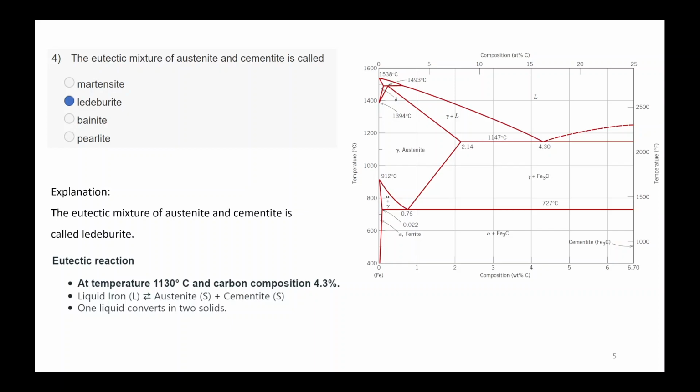Then below that, they have given two lines, the martensite start, MS, and the martensite finish, MF. Start and finish, yes. So above coarse bainite, what is there? Feathery bainite. Yes.